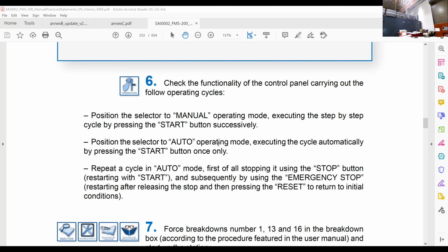So step 10 starts a sequence for the feeder board, loading manipulator, and so on. Step 30 is for the inductive sensor. That starts where it turns on before it can work. Step 40 is for the capacitive sensor. Step 50 is for the photoelectric, the photo light. Step 60 is the initial step of the measuring process, which is the stroke read on the cylinder. Step 70 is the evacuator that gets the bad part out and rejects it.